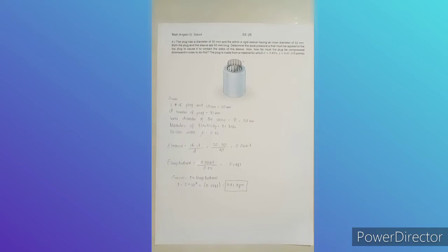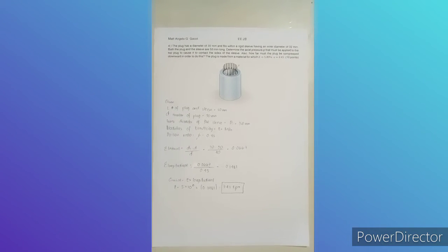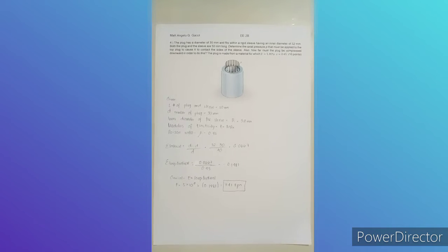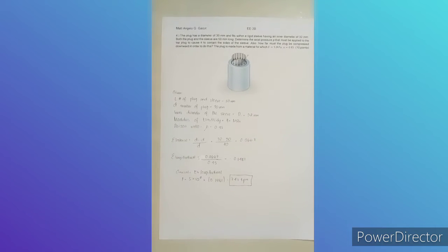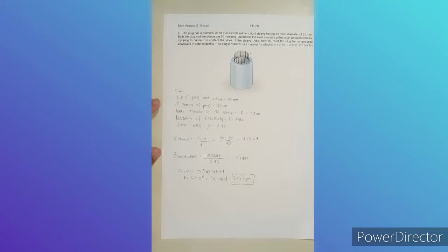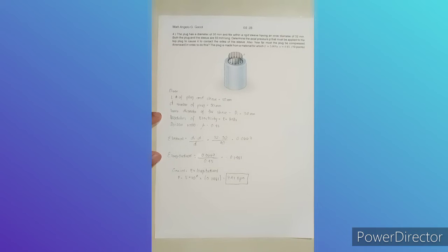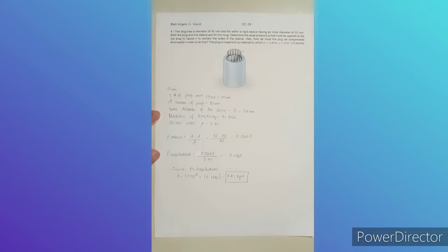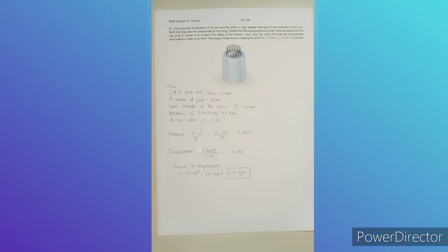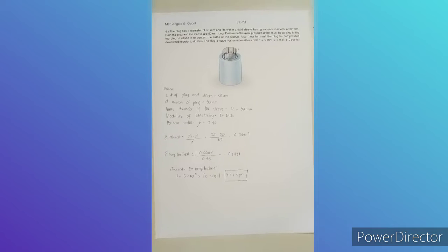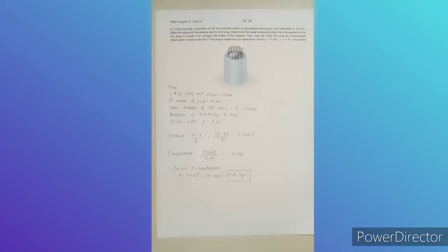The plug is made from a material for which E is equal to 5 megapascal, ν is equal to 0.45. So given, the length of the plug and sleeve is 50 millimeter, the diameter of the plug is equal to 30 millimeter, the inner diameter of the sleeve, which is our Di, is equal to 32 millimeter, the modulus of elasticity, our E, is equal to 5 MPa or megapascal, the Poisson ratio, the ν, is equal to 0.45.